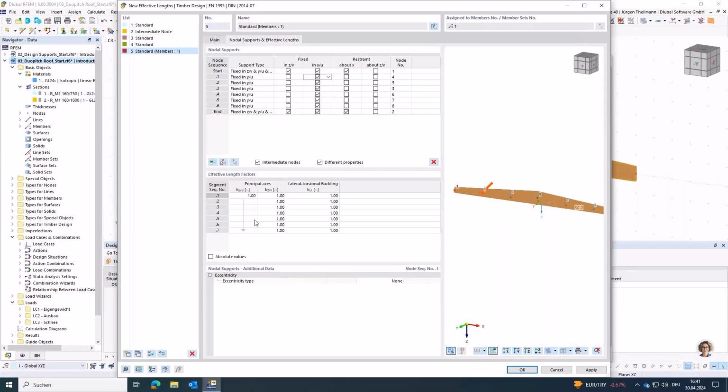This directly affects our effective length vector for this. So we have a critical length that spans from one side to another of the beam for buckling around the major axis, and just for these small segments between the lateral supports around the minor axis.